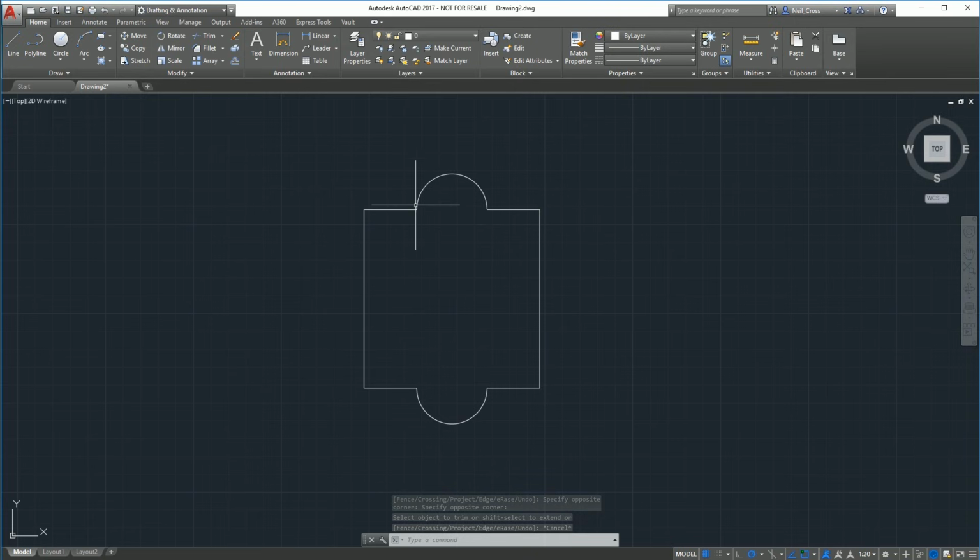Maybe it's like a metal plate with two flaps, top and bottom. If you go on a proper Autodesk training course at a reseller or something like that, you'll hear the expression overused, design intent, right? You capture the design intent. We're all about capturing the design intent. Whilst the expression makes me cringe somewhat, there is some merit to it. In that if you intend for this design to be a certain way, you put in constraints to force the objects to respect your design intent.